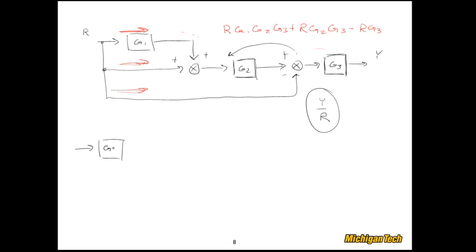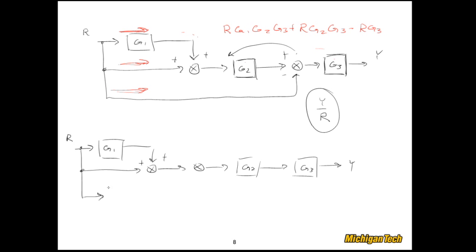And by the way, when you're doing block diagram reduction, you'll find that you need quite a bit of paper, because you're constantly redrawing these blocks. Okay, so I'm going to go ahead and move that summing junction to there, and I'll just stick in our G2 and our G3, which of course will combine very nicely into series. And then let's see, make sure I get these plus signs. And then we have this pick-off point, and it's going to go into some kind of block that goes here. And to maintain these signs, this one's a plus, that one's a minus.